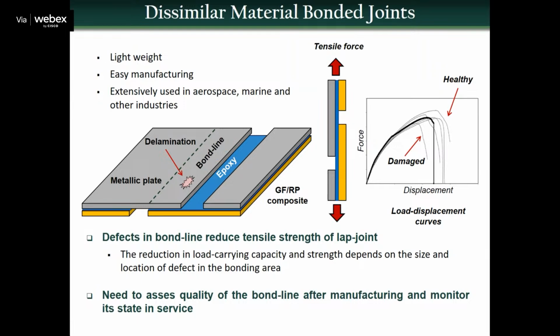Well, this is actually a joint that will bring challenges in the maintenance because they are dissimilar in material properties. So when you are subject to the same loading, the loading can be mechanical loadings, it can be thermal loadings, for example, the change of the temperature. Due to the differences in material properties, the cracks are more easily developed at a dissimilar material joining location.